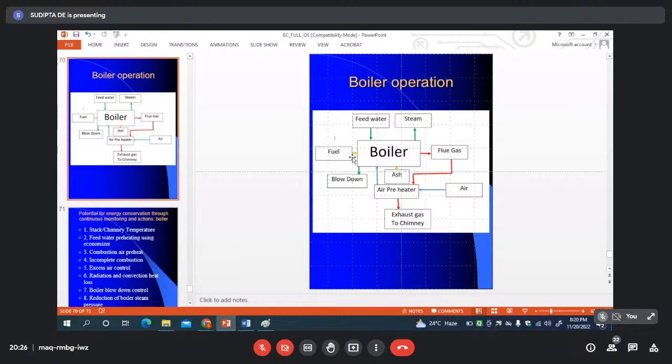So you have to clean those deposits regularly at an interval, either continuously or at an interval, so that the scale formation possibility is reduced as much as possible. This is called the boiler blowdown process. It is done by extracting some water from the boiler's bottommost point.